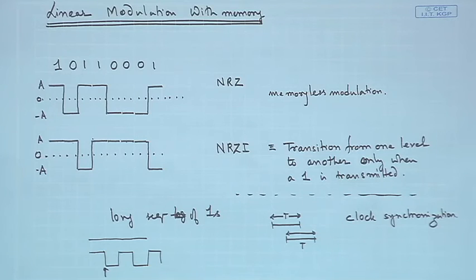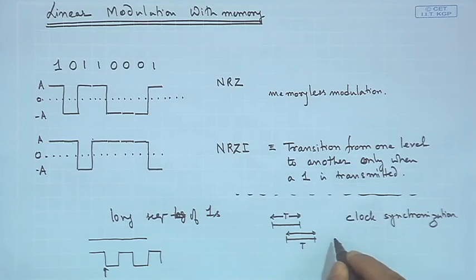Then one could say that, in this case, if there is a sequence of zeros, then you have a problem, but of course, those could be handled in many other ways by mixing the zeros and ones, by XOR and many other operations. So, this is highly beneficial in clock recovery. There are many other techniques like the Miller code, and many others. We just show one of the schemes over here to identify how this works.